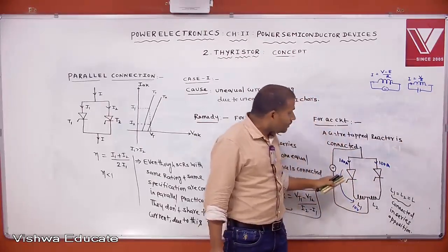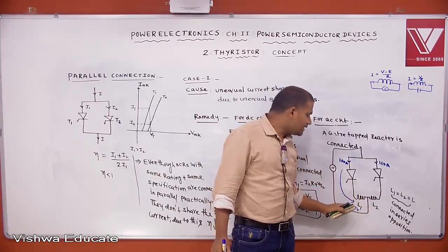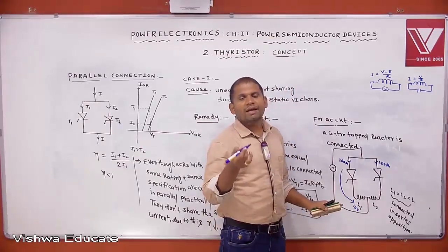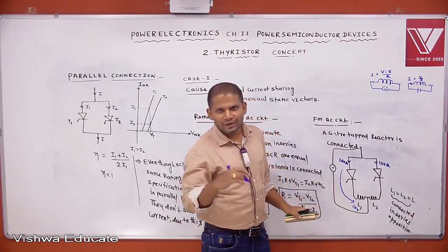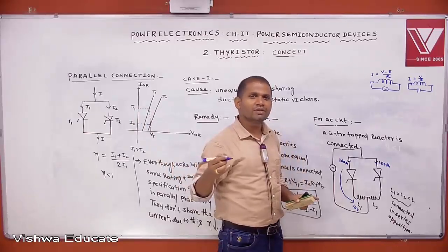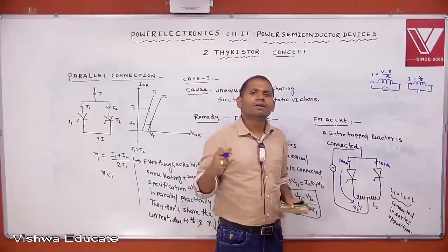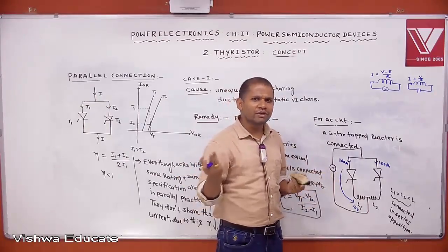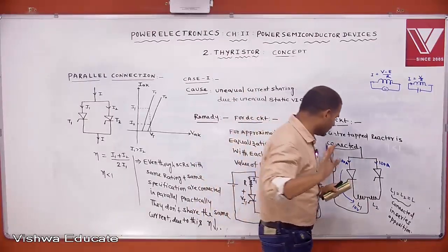That means, if any alternating current is passing through the L1 coil, let us assume there is an induced EMF of 10 volts. That induced EMF is called statically induced EMF: if the conductors are stationary and the flux is variable. That in detail you know from other subjects, that is electrical machines. If the conductors are moving and the flux is stationary, whatever EMF is induced is called dynamically induced EMF. That concept we mainly use in the DC generator. The statically induced EMF concept we use in the transformer. That fundamental you know.